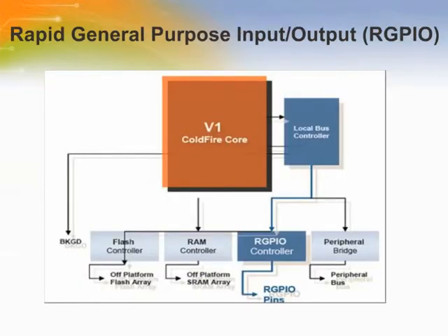The Rapid GPIO module provides a 16-bit general-purpose I/O module directly connected to the processor's high-speed 32-bit local platform bus. This connection to the processor's high-speed platform bus plus support for single-cycle, zero-wait state data transfers allows the RGPIO module to provide improved pin performance when compared to more traditional GPIO modules located on the internal slave peripheral bus.